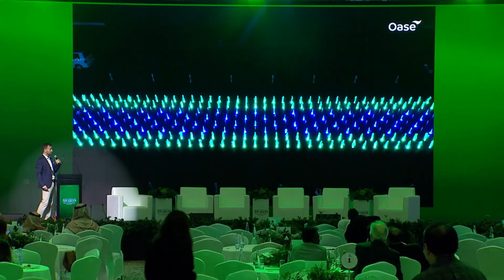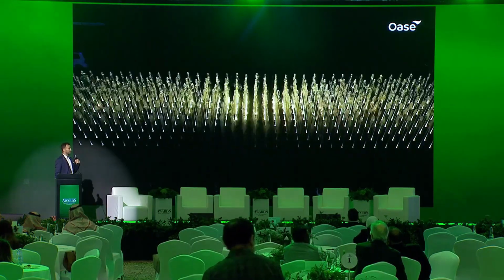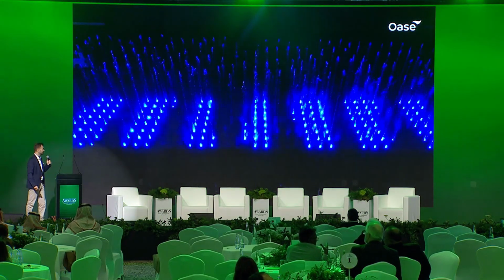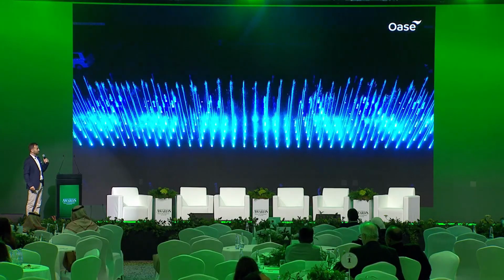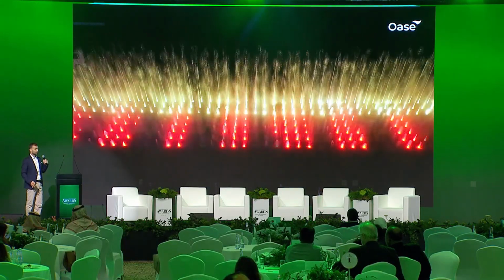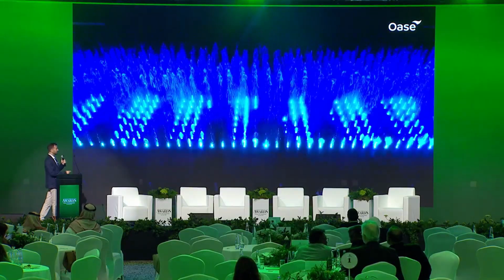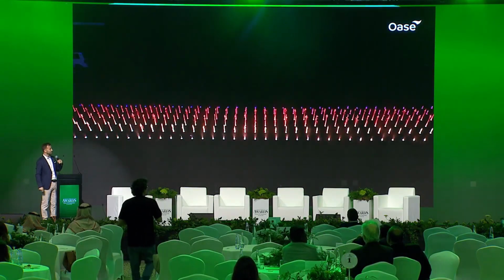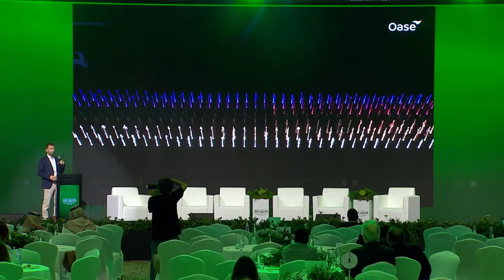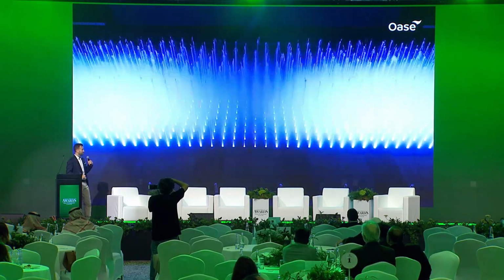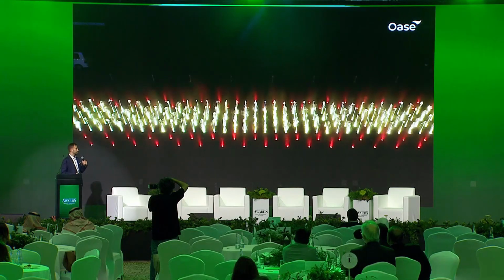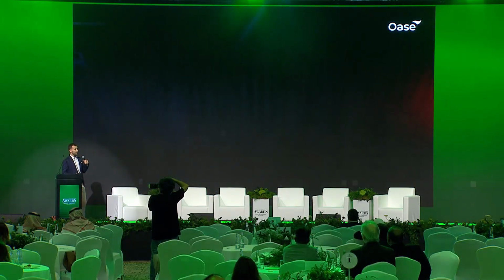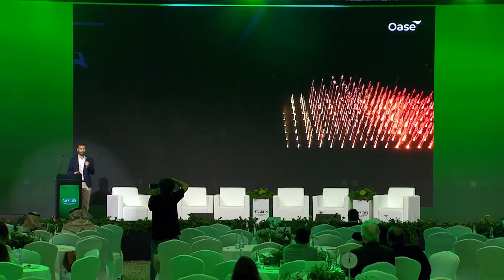So that video is a very good example. This shows the capabilities of a water feature and the technology behind it nowadays. Here you can see every single jet is individually controllable in speed, height and color, and it's a modular system. So here you actually have a complete pool behind the surface. You have a low voltage pump system, lights, underwater drivers, power supplies, everything inside the pool. And that gives you endless capability for the show programming as well.